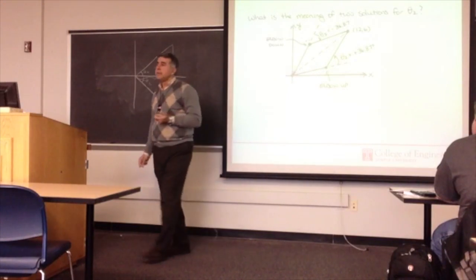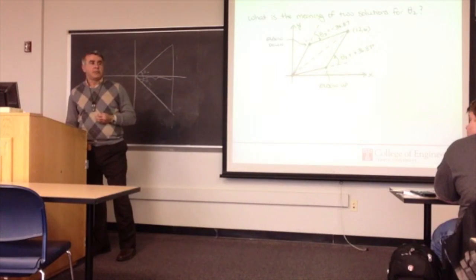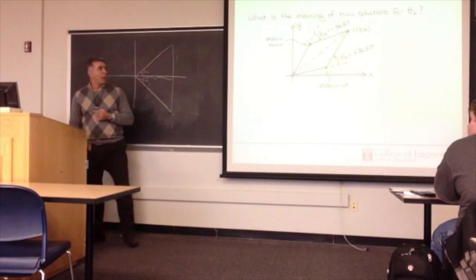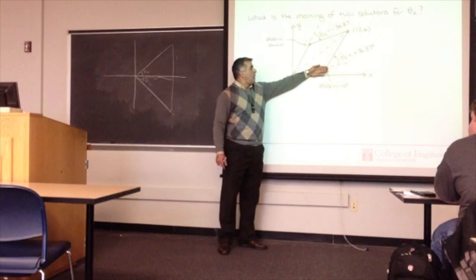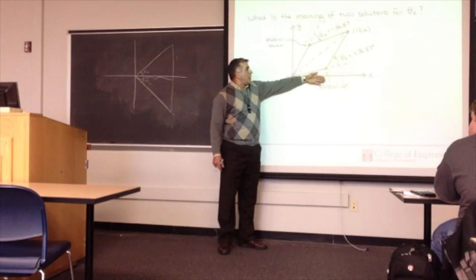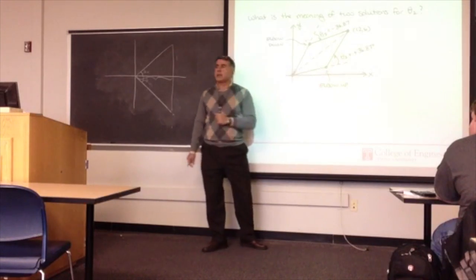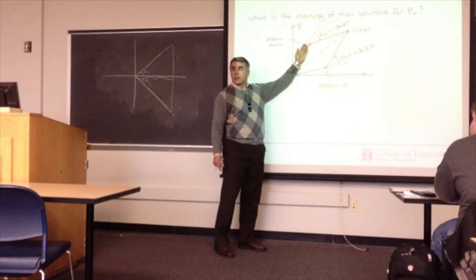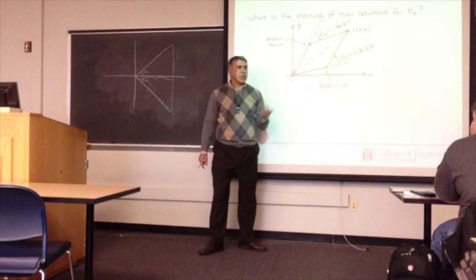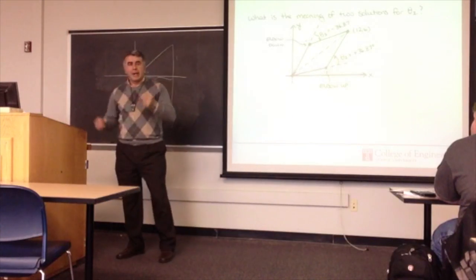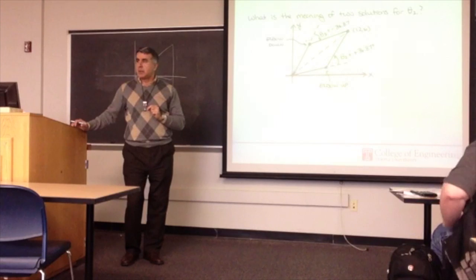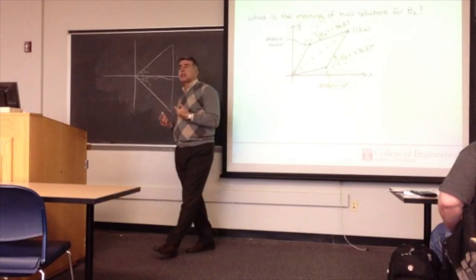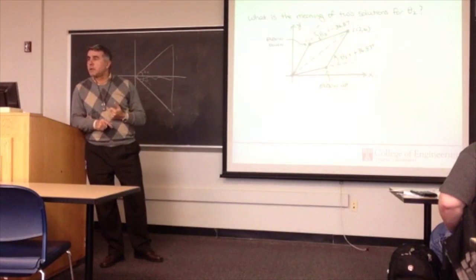which one should I choose? Okay? So, in those cases, then you want to find the quickest solution. For your arm to move from horizontal to here or to there, which one takes longer? This one? Takes longer, right? So if efficiency is important for me in robotics, and I want to get to that position fast, then I would go with this one. That's how you make your selection in terms of the positioning of your robots.